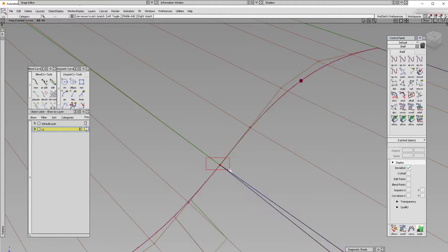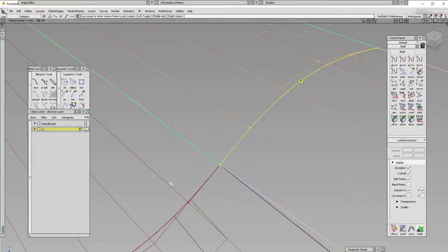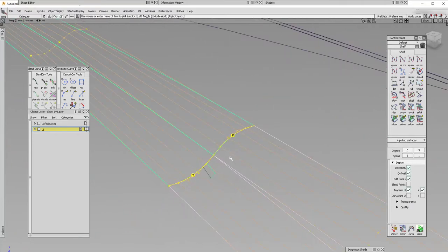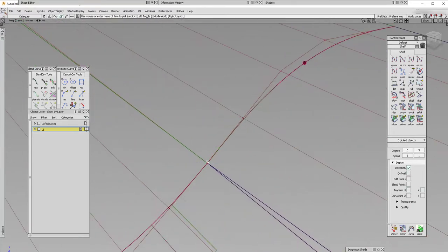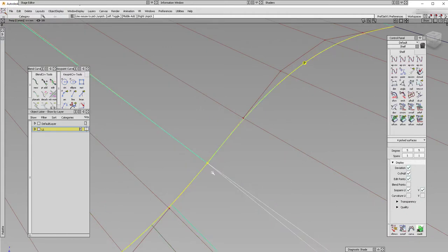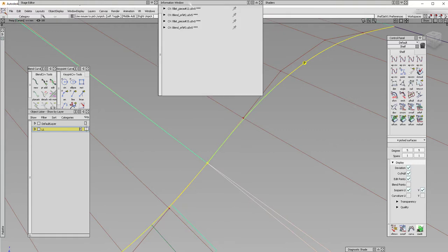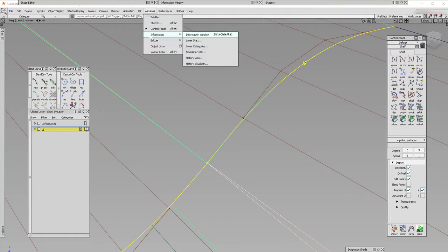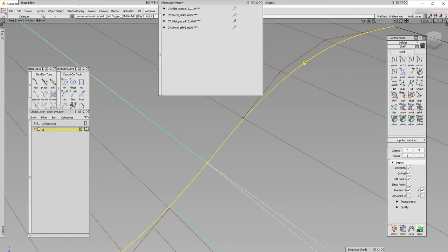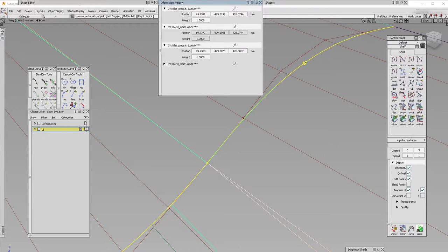But there are slight differences between. I opened the 4 fillets' CVs and then selected all of these intersected CVs, coming here to the information window menu, and checking their positions. You see there are differences. I can change these.